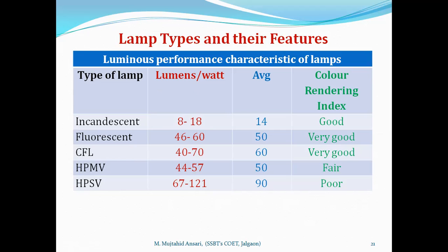If your wall is painted a dark color, definitely the light reaching the working floor is small. Again, it depends upon the voltage variation. The change in voltage very much affects the light output of the incandescent lamp. If it is not getting the proper voltage, the light output will be smaller and the heat energy will be more. We have already discussed this in detail.